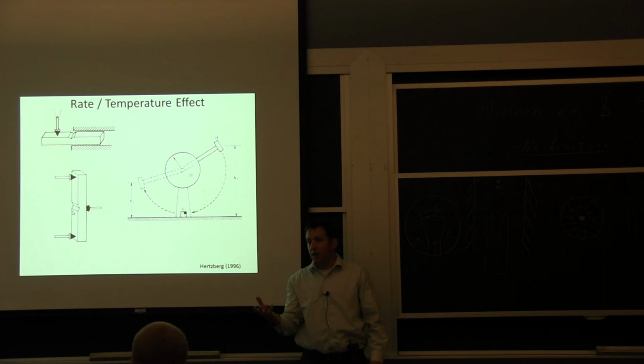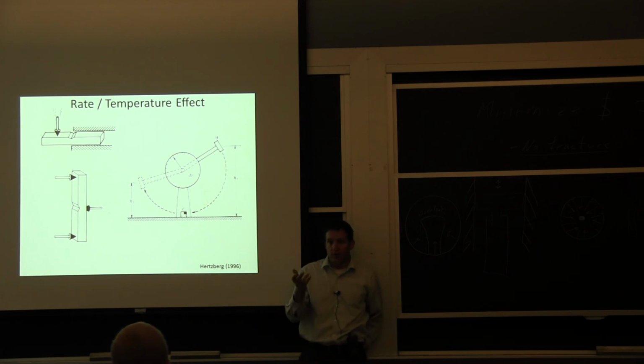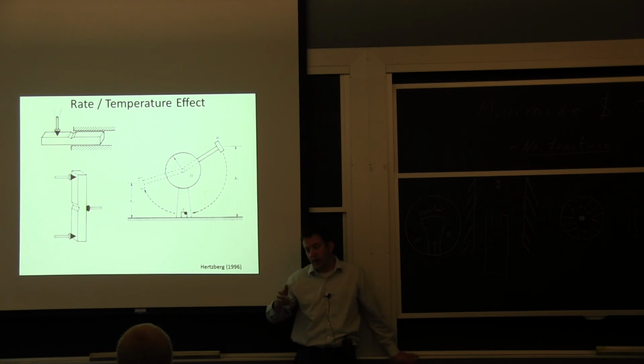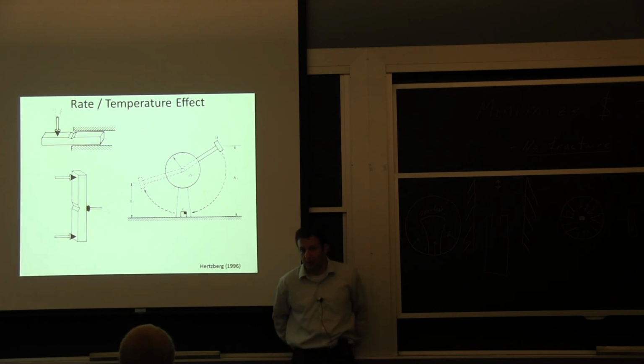The orientation does matter. If you're looking at a pressure vessel that's thick, maybe you want to see if the crack is going to be a laminar type of crack as opposed to a transverse crack. So the way you cut that bar makes a difference. And you're just looking at the energy loss to get the pendulum across.